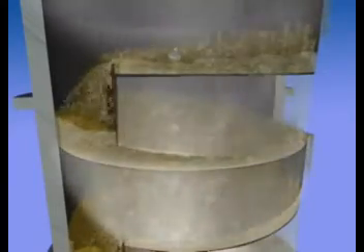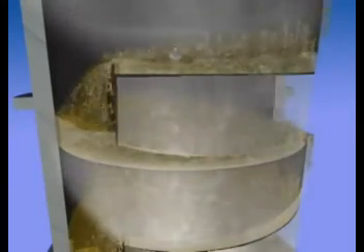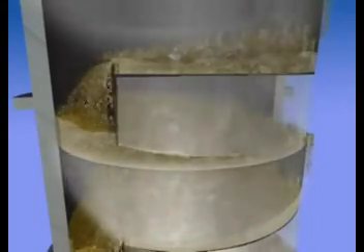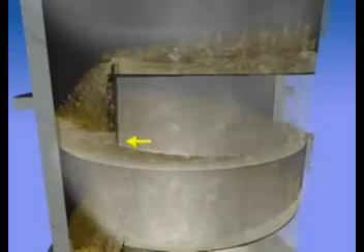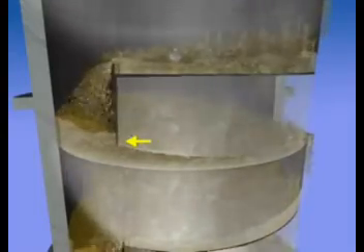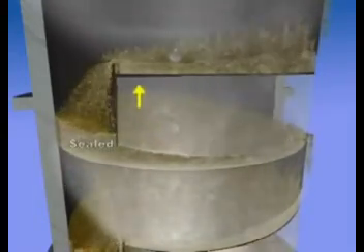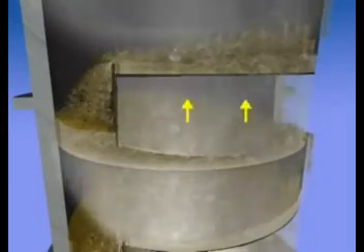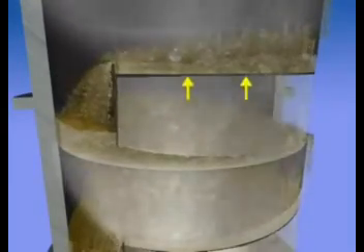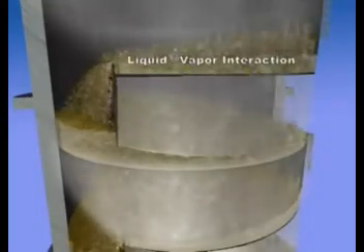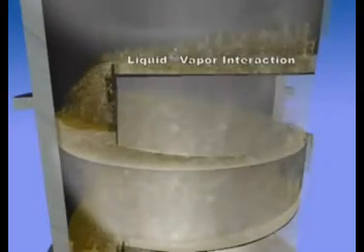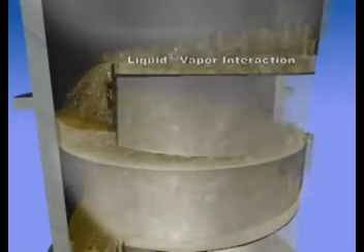Components that vaporized at lower boiling temperatures create an upflow of vapor. During normal operation, the vapors cannot enter the downcomer area as the liquid properly seals the passage. The vapors are forced through the bubble caps on the tray above. Therefore, as the bubble caps are submerged in the liquid, the interaction between vapor and liquid is maximized. Bubble cap trays are particularly efficient for accomplishing the interaction.